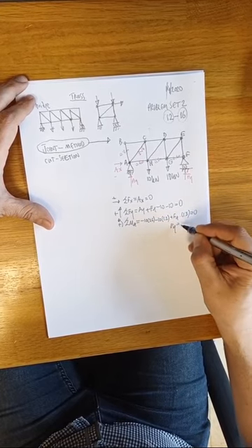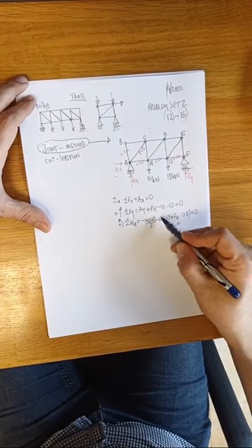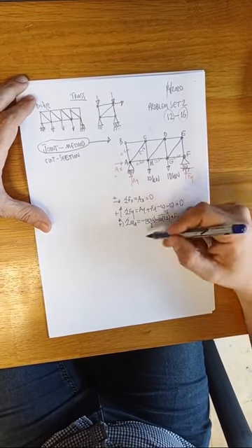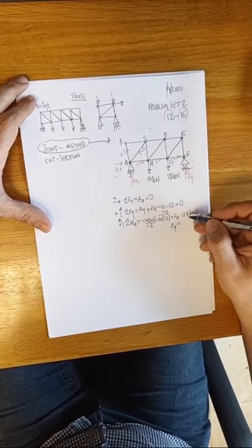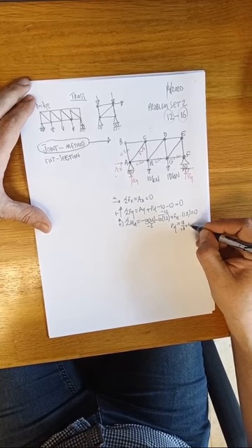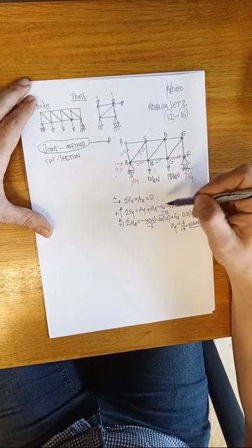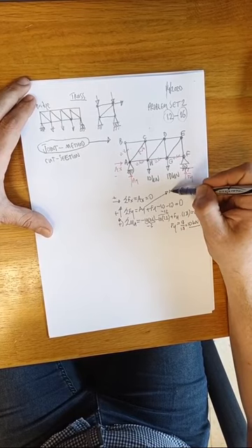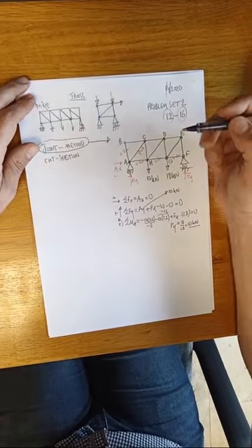What is Fy from here? You see, this is 6, this is 12, so minus 12 minus 6 actually, then 18. 18 divided by 1.8 gives you 10 kilonewtons. So easily Ay will also be 10 kilonewtons. These are the reaction forces. Let's pass now to our topic.